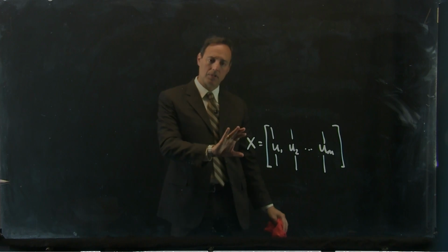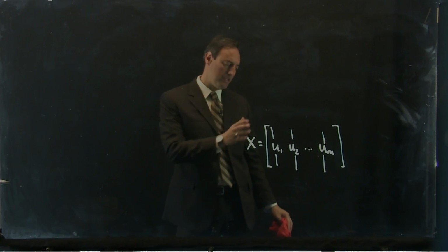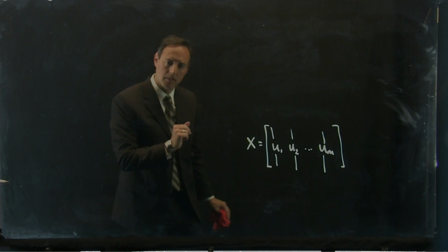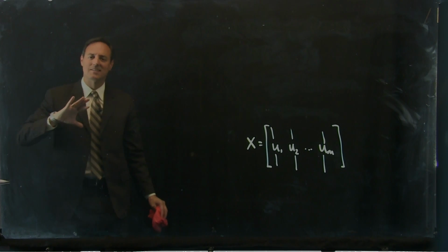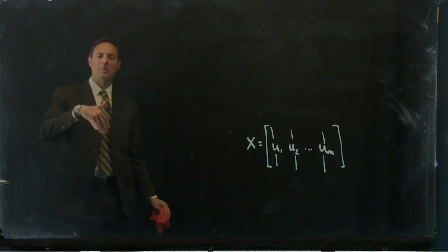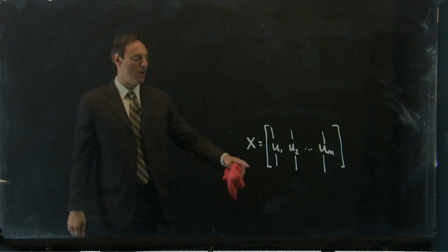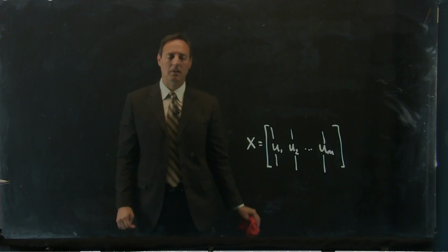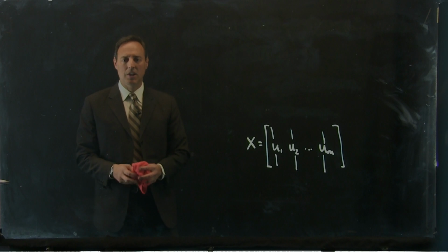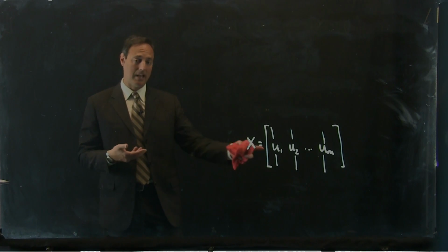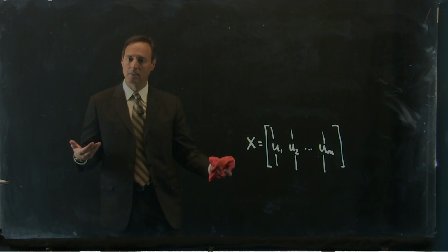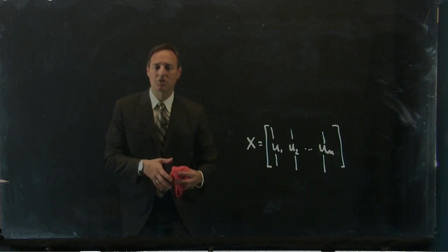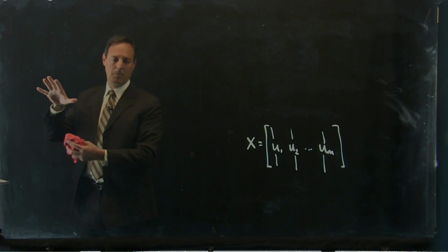So for instance, in this simulation here, if I take a snapshot of the data, the only things I can describe, or the only basis sets that can give me, are things that are actually observed in this simulation. In other words, just because I get a POD basis set out of this, using the SVD, does not mean I can generically represent any solution of my PDE.